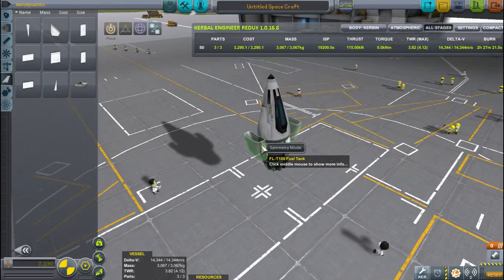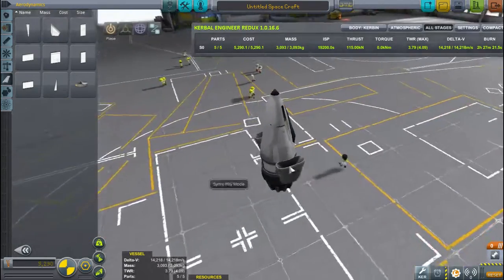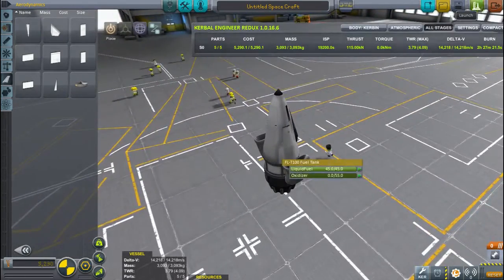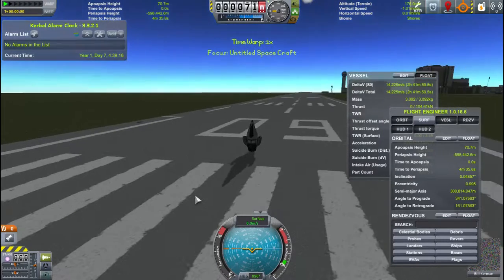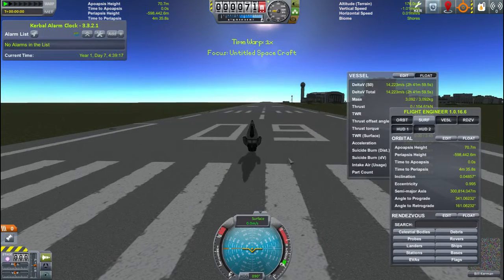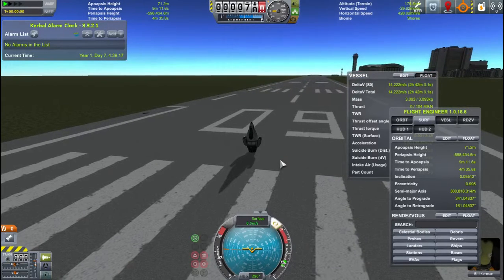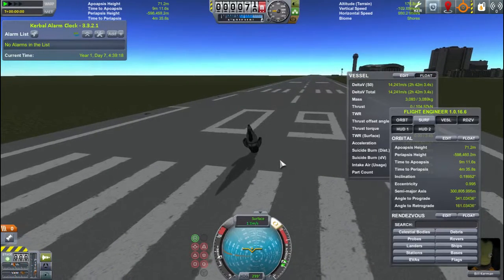This one too. Let me put that on now. We will be able to take off, albeit with a lot of drag. That's the disadvantage of using these air intakes, is that they not only have drag because they stick out, but also they have intrinsic drag as well.